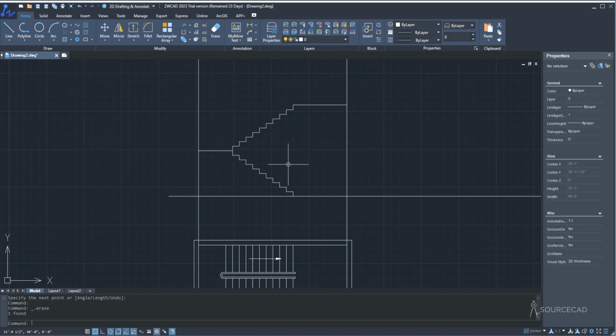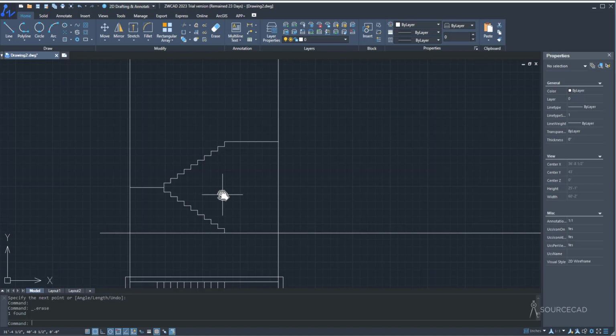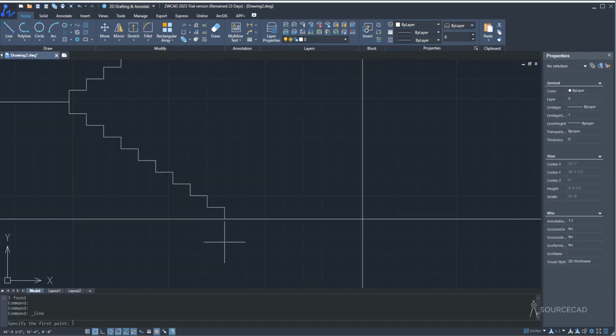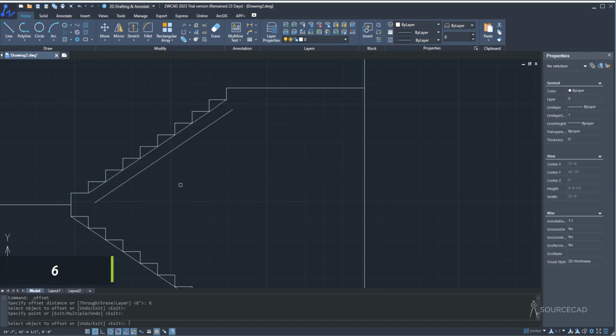Okay, so that's the basic shape here, but of course that's just not complete picture. So I'll delete this ray and let's add the details here, which is quite important, of course. So for the details, I'm going to select the line tool, and here I'll select this line and I'll select this one, actually these 2 points, which is making no sense at all for now, but let's just add it like this and this. Now let's go to offset and offset this line. So the offset distance is 6, enter, select offset here, select offset here, done.